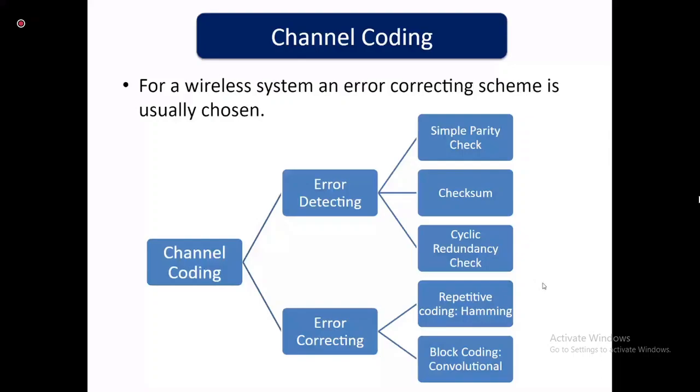There is a reason. Now, error correction systems, Hamming, you might have seen this or read it somewhere, that Hamming is only capable of detecting up to 2 bit errors and correcting 1 bit error. Convolutional coding is not the same. It will actually be able to correct most errors that are there in your signal or your bit stream. But the problem is convolutional encoding multiplies your data volume a lot.